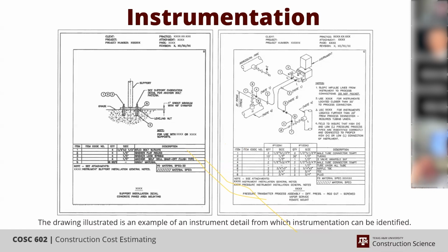If you have, like the example I gave earlier, a temperature element or pressure gauge that threads straight into the pipe, there is not going to be an instrument detail for that, because the OLET that the instrument is threaded into is all that it needs. And so it's just going to thread in, and you'll see what it's reading right there at the gauge. It's going to be a local gauge.